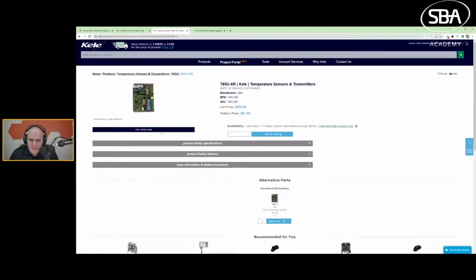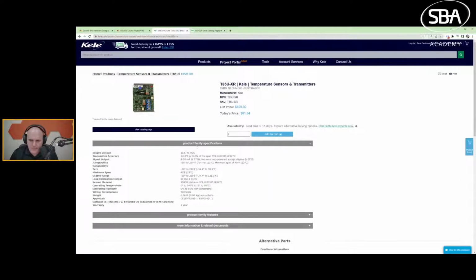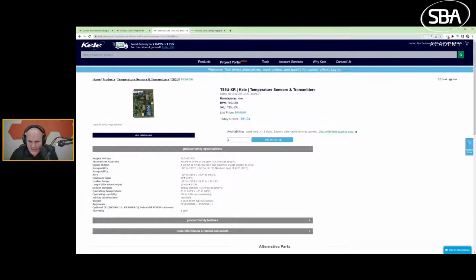So this is just a sensor board. I see. So what this sensor board allows us to do is take an input, it looks like, and then give us an output. So we're able to put an input in and drive an output out, if I'm reading this correctly. So that would be one way it looks like that we can convert this to a 4 to 20 milliamp signal. I'm not sure if that's going to be acceptable per the spec. We'd have to RFI that out, but it's super expensive versus just a normal 1K platinum or 1K nickel. Let's do some outputs though.